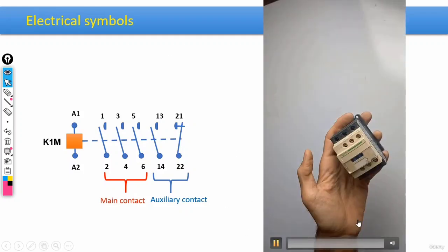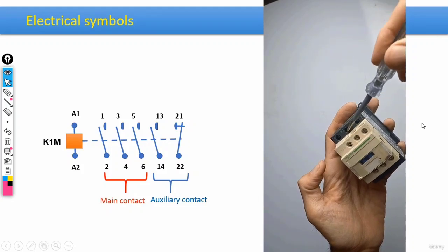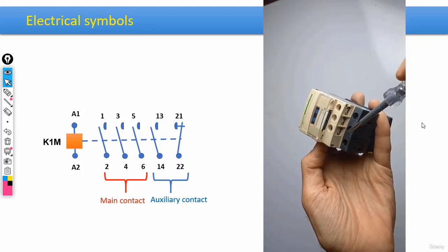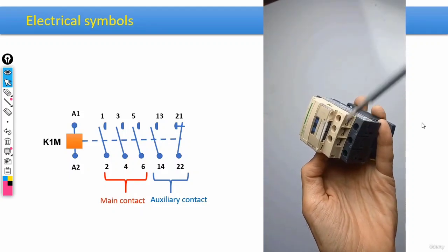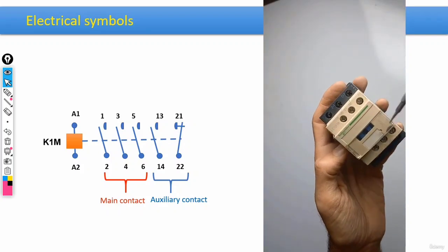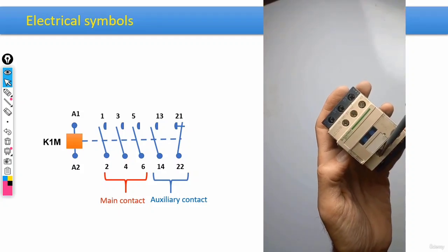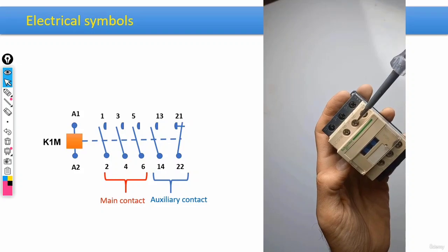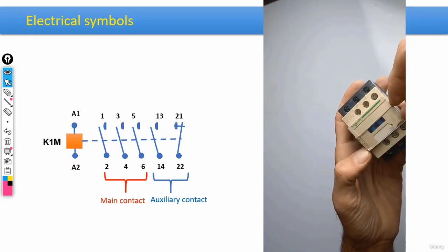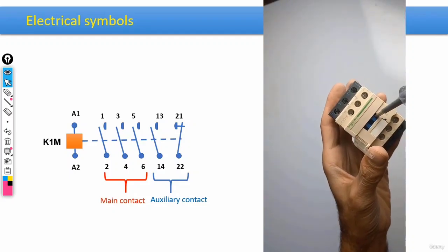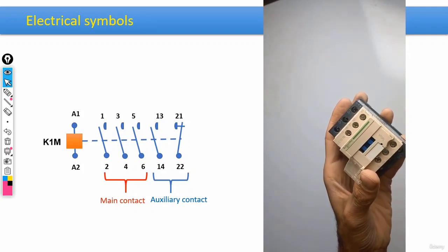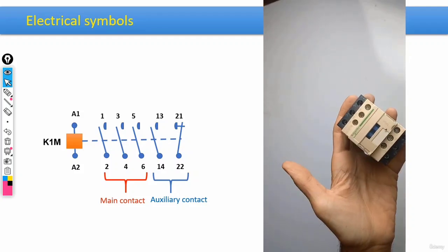In the video, we'll get a close-up view on the contactor. Like, for example, we got the terminals here, the L terminals, and then on the other side, we have the T terminals, okay? Then we have the bobbin terminals, more precisely A1 and A2. We also have the auxiliary contacts, terminals 13 and 14, as well as 21 and 22. And by the way, guys, we are able to activate this contactor manually, and it would be completely like this, quite easily. And yeah, that would be all for the concept of contactors.